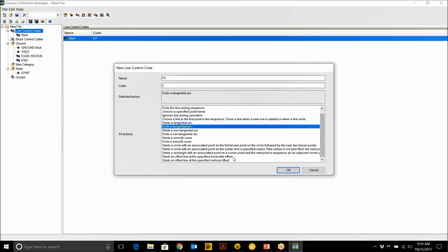I have not tried that, and that is something awesome that should probably be tried out. I'll have to get back and put that answer up on the blog. I'll go try that today. I'll go shoot a back of a curb, and I'll offset the top and offset the gutter pan and see if that gives me a vertical and a horizontal offset line. That'd be very quick and very useful for a surveyor. I haven't thought of that. So, James, if you could check our blog later this afternoon or tomorrow morning, we'll have an answer up there for you on that.